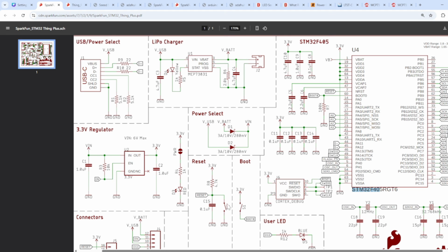Now the moment you press this, there is no resistor on this path, so it becomes a low impedance path, and the BOOT0 pin will get pulled up. So this is how the application works when it comes to pull up and pull down.